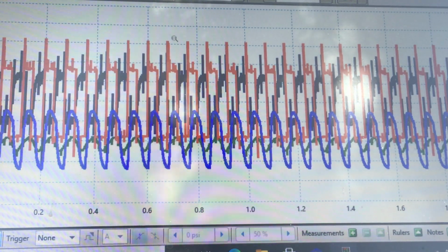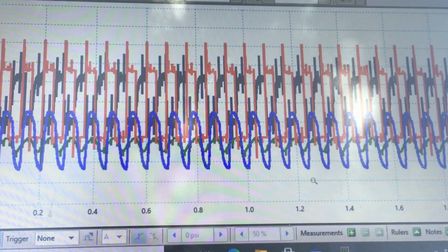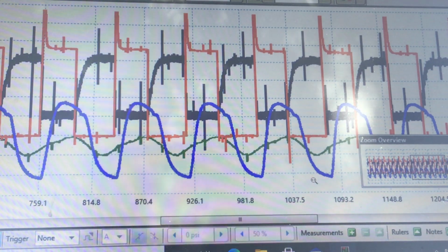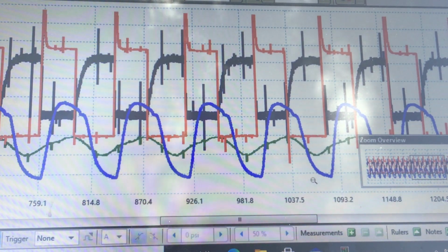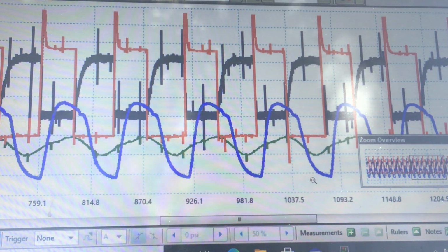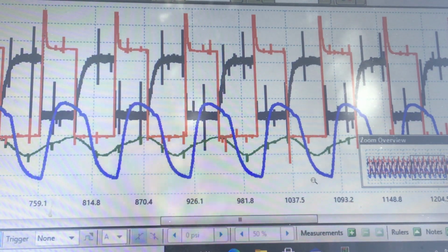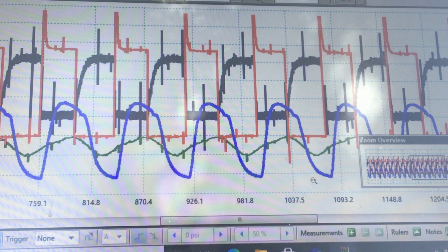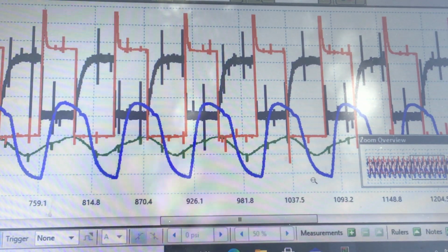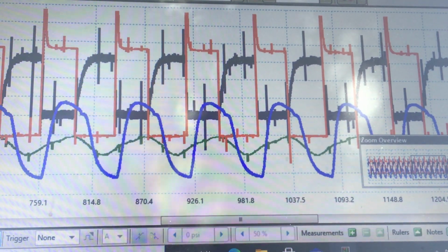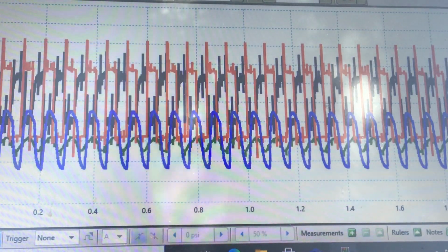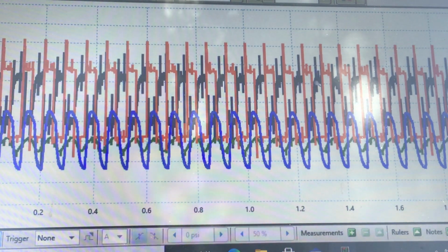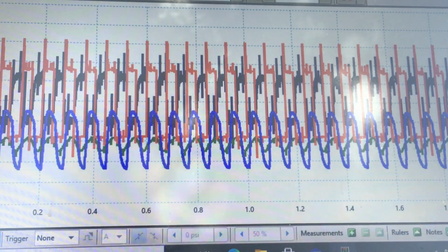But one thing we can infer is that we know this solenoid moved because we see a dynamic vacuum change in 2 different spots. We see it on the WPS and we see it on the fuel tank pressure sensor on the car. So that's definitely a validation that this solenoid lifted, the system got a shot of vacuum, and then it closed real fast. It's a frequency type solenoid, but nonetheless, let's go down the capture and see if we can see anything else.